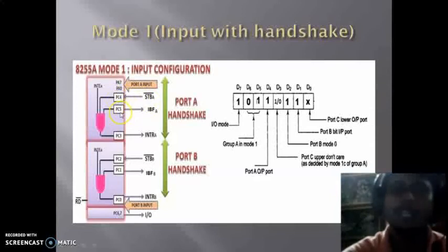After receiving the data, the 8255A sends an acknowledgement signal, the input buffer full, telling the peripheral device that I already received the data.